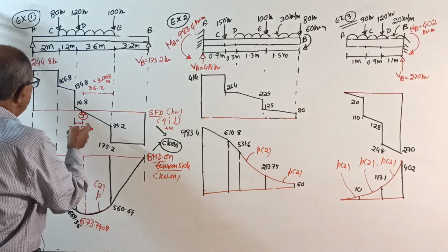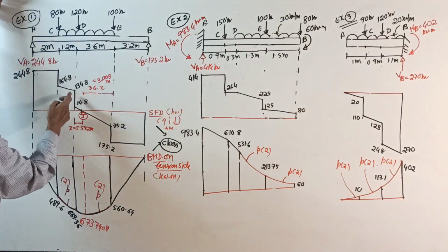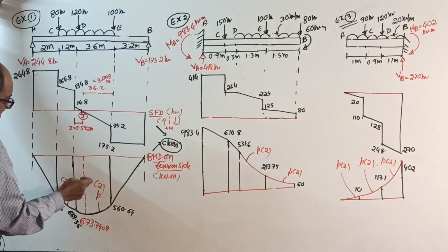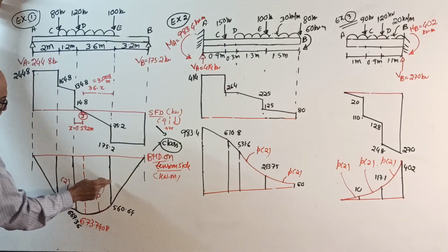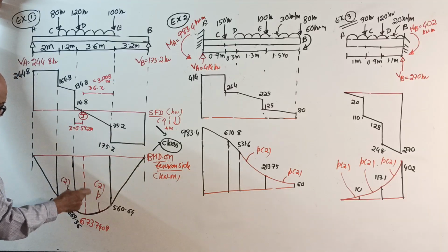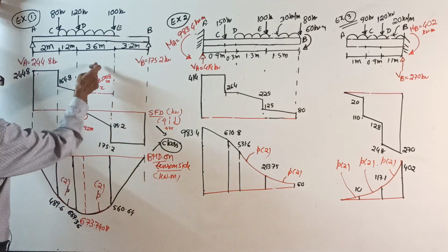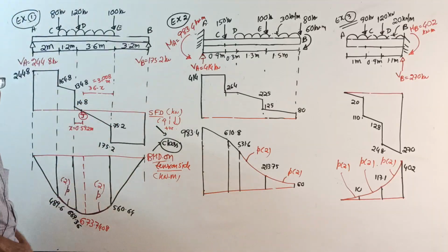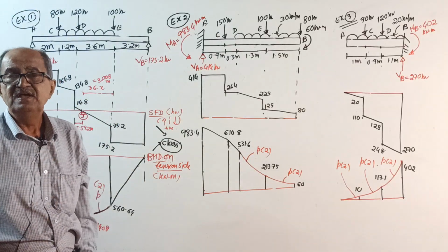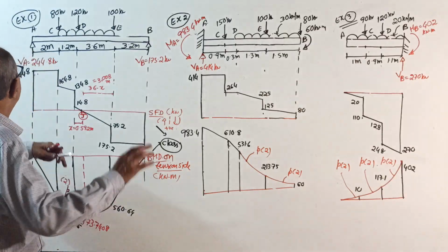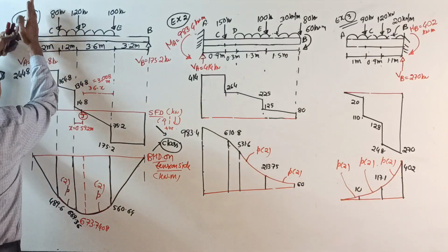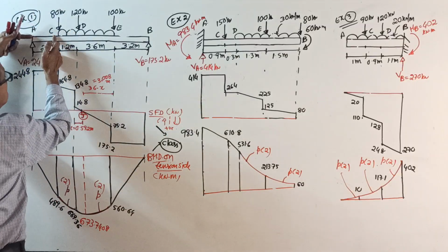First question: you draw the shearing force diagram, locate the point where SFD crosses the baseline, then find the BM at all the points and also find the BM there, which is the maximum BM for this beam. Then you get SFD and BMD. See, I was in two minds. Right now, shall I explain once again? See, shear force diagram: go up by 244.8. No load up to here.